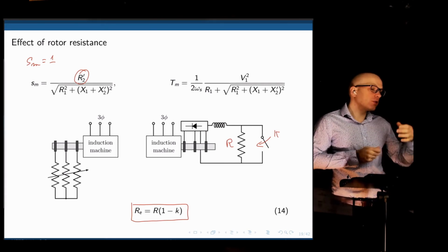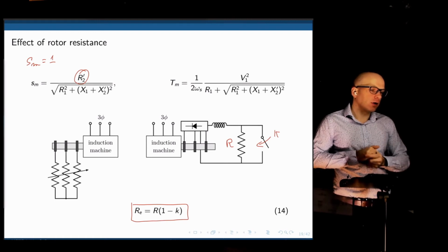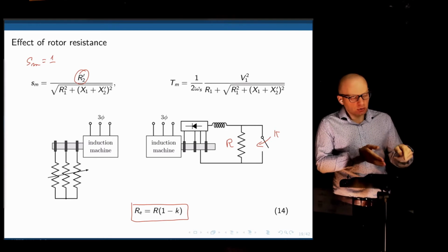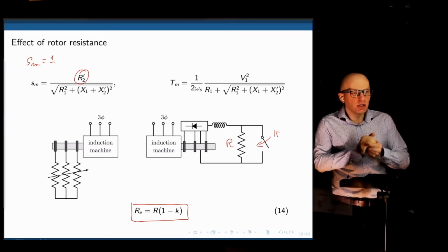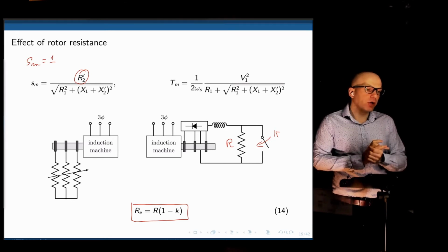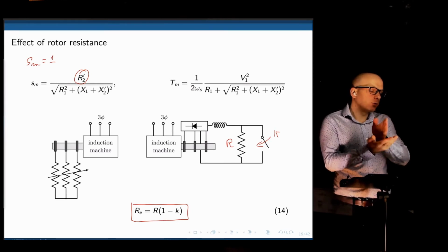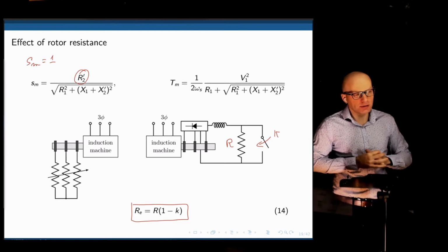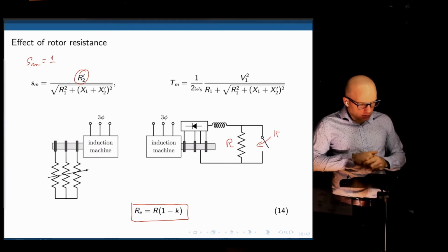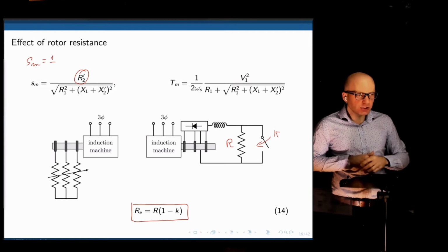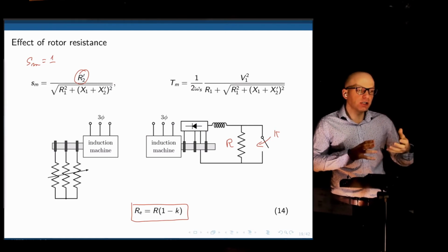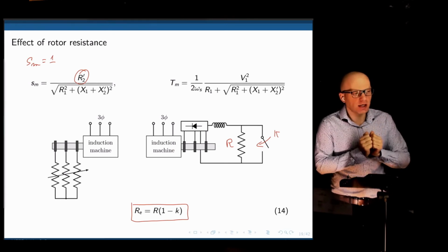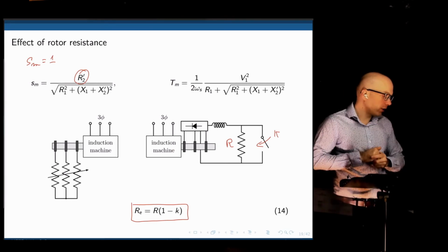If you want to drive a specific load at a specific speed, you can arrange this duty cycle to give you the exact resistance you need to shift the slip point so that you get the maximum torque at the exact speed the motor is operating at. Or simply attach a resistance when the motor is at start, and once the rotor starts to speed up, you can shorten that resistance and go back to a normal operating mode.